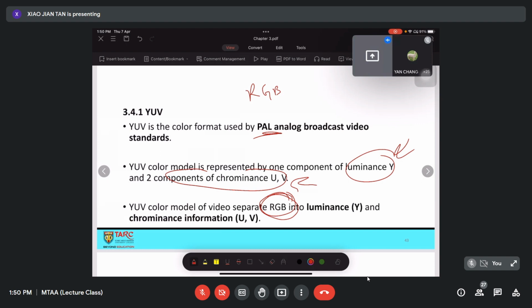For example, you scale down the R, maybe originally 300 times 300, but you scale down the R to 100 times 300, but remain unchanged G and B. So when you combine later on, for sure you cannot combine. That is because you cannot simply process only one of the channels and ignore the rest of it. But in YUV, you can do so. That is the logic behind the JPEG compression, right?